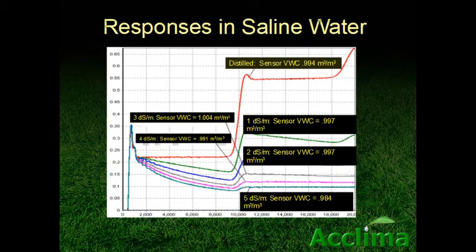Following that is an impedance mismatch area where the electronics connect to the waveguide, and the whole of that connection is inside the enclosure. At this point, the wave hits the water. As you can see, with distilled water, there is no attenuation of the wave. The reflected wave occurs at this point, and this particular TDR reported a fractional volumetric water content of 0.994.